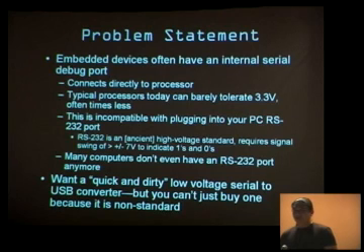Embedded devices often have an internal serial debug port that's connected directly to a processor, right? Processors today aren't like processors a bazillion years ago when we designed RS-232. RS-232 was made in the 60s or something like that, and it uses plus or minus 7 volts for signaling, which is not compatible with your processor. You plug an RS-232 port into your processor, you'll burn it out, right? So a lot of computers don't even have an RS-232 port on them. This one here, my laptop, does not have an RS-232 port.